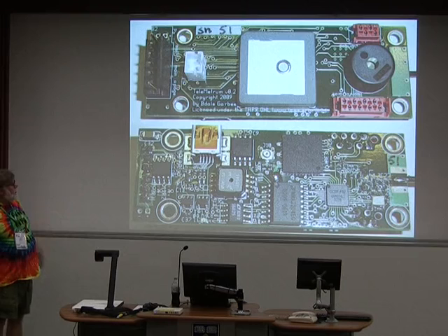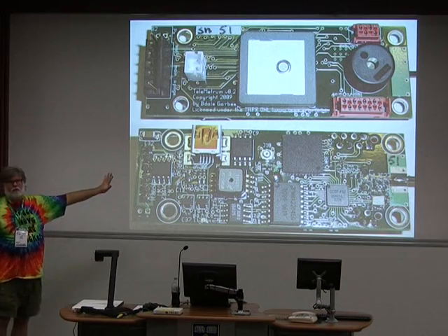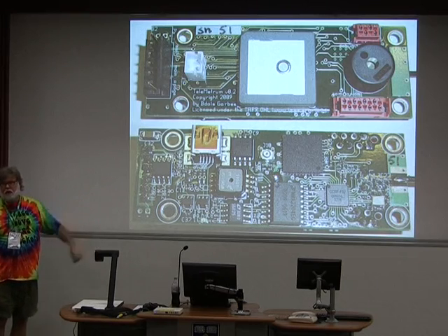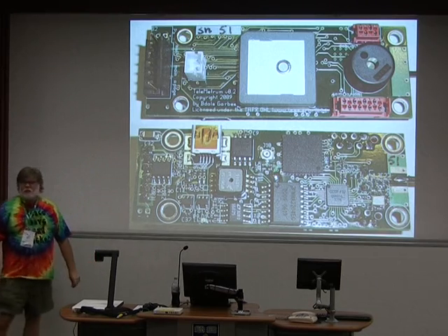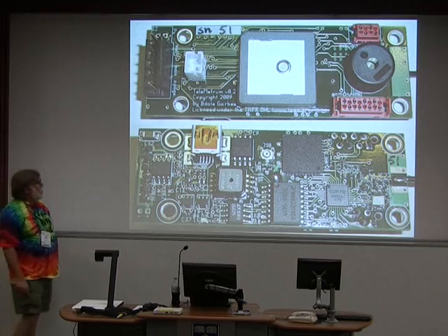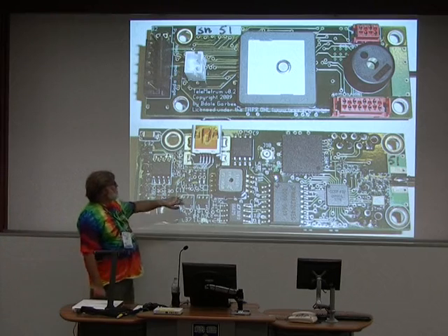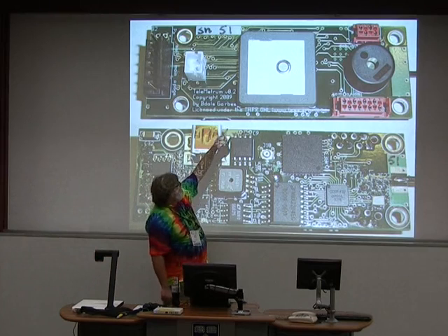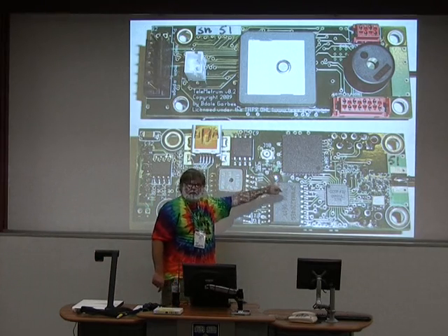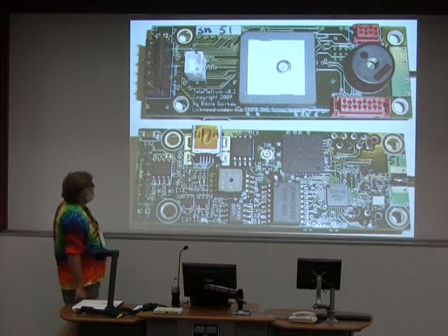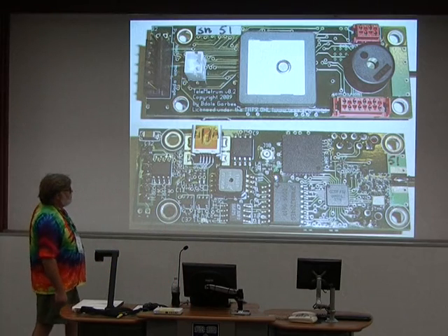The consequence of that was that I could still hand load the board at home and reflow it in my electric skillet, and then hand load the through-hole parts from the other side of the board, and we got the area advantage of, you notice where the big GPS patch antenna is. This is the only impact on this side of the board, where the center pin gets soldered through, and it was a much more efficient use of space.